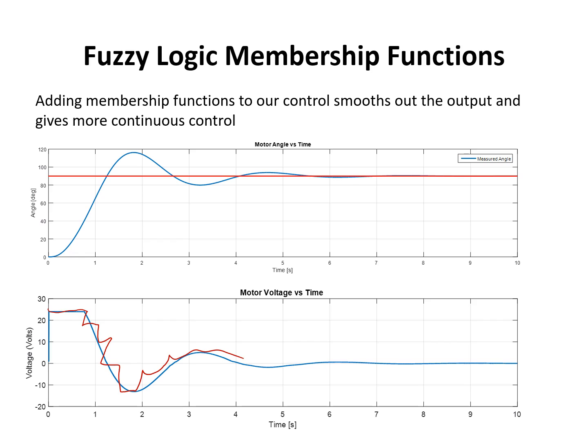And the advantage of fuzzy logic is that if you can formulate a solution verbally or logically, then you can implement a control at least. Whereas for the PID, typically, if you're trying to formulate it properly, you firstly have to develop the plant of the system and then develop the controller, going through all those aspects of the development of the system before you can actually implement it, unless you do manual tuning.